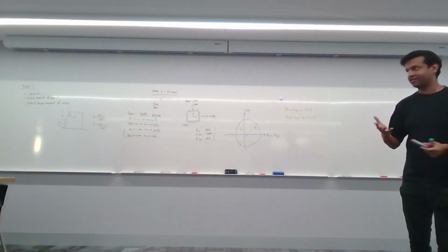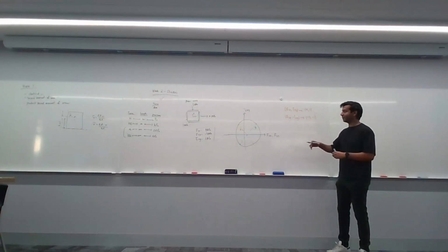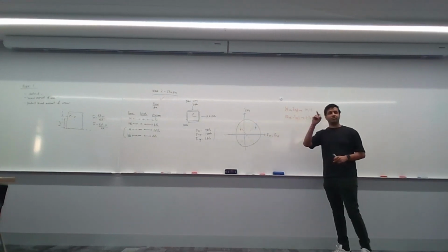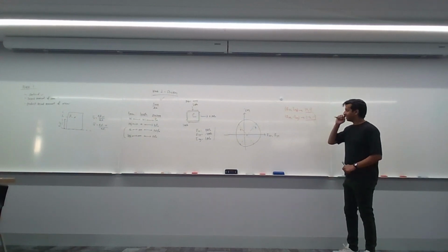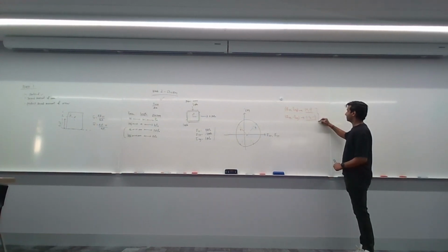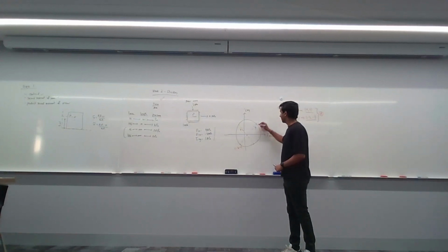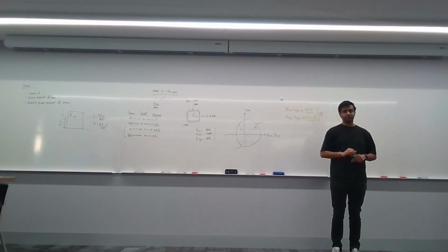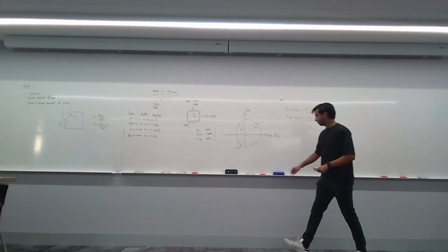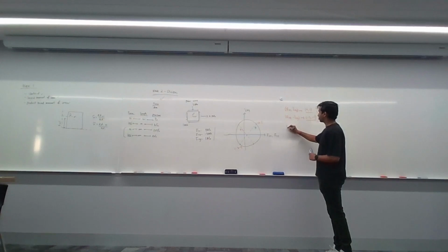B, right? So remember, that's how you figure out where you are on the Mohr circle. For any given state, the points that you plot on your Mohr circle are these, right? So, in this case, this would be scenario B, right? Because this will be negative 3, negative 1, and this side will be 4, 1. That's how you plot it on the Mohr circle. Okay? Now, again, for stress Mohr circle, you also have your stress transformation formulas.